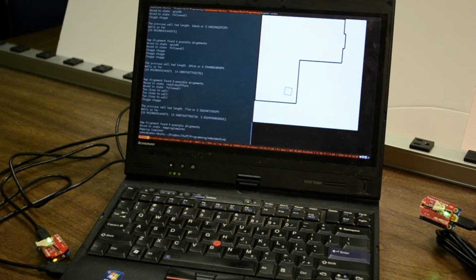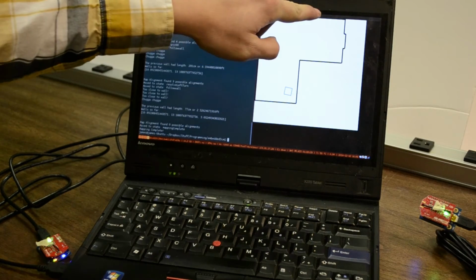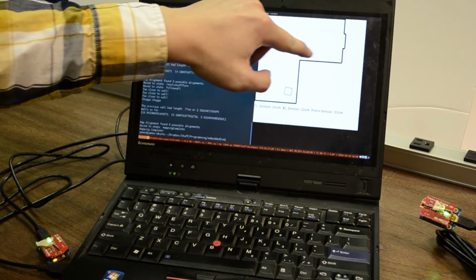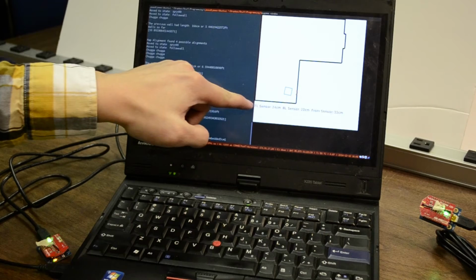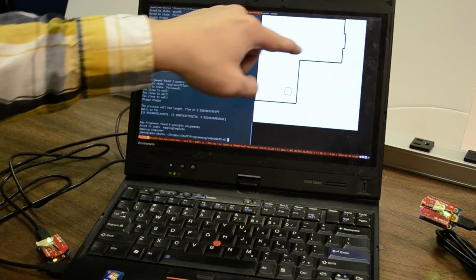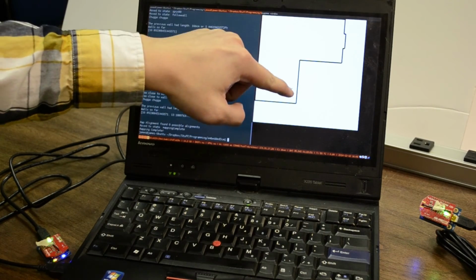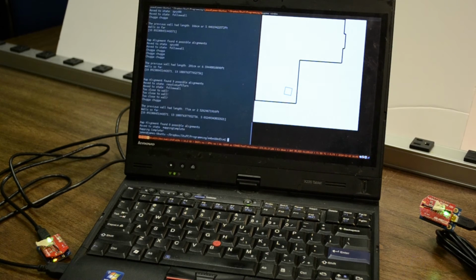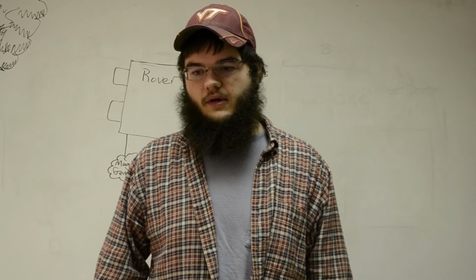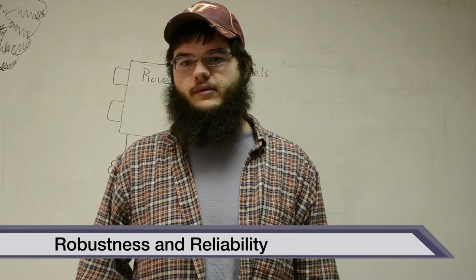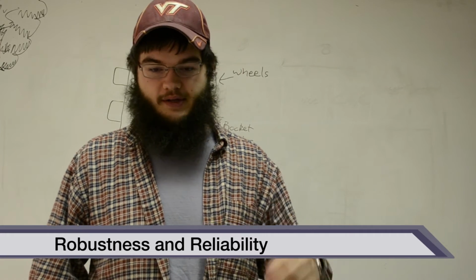And then it'll continue until it has followed enough walls to determine that it is at the end of the wall that it knows. In this instance, it follows the first two walls and realizes that those two walls could still be these two down here. So it'll follow one more, and at that point it knows there's only one possible location, one possible wall that it could be aligned to at that point. It'll stop.